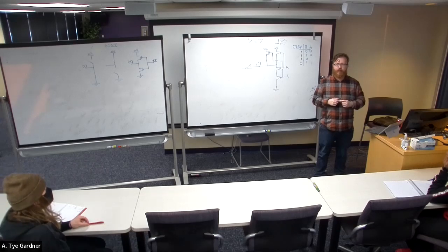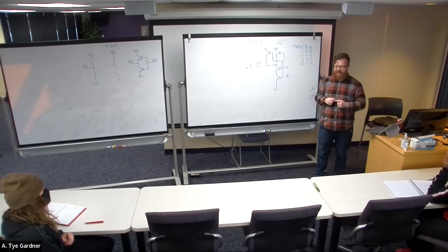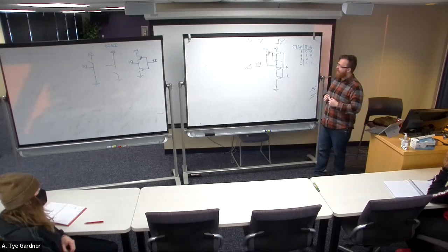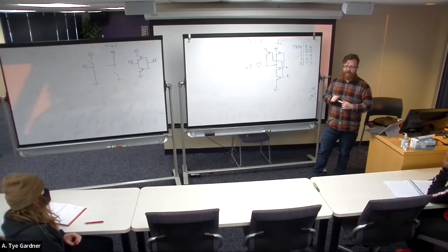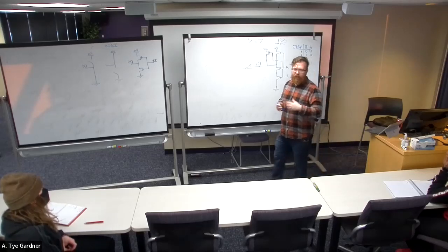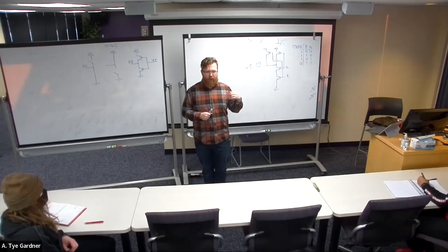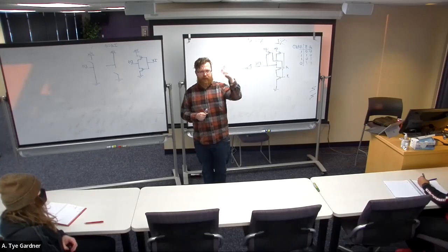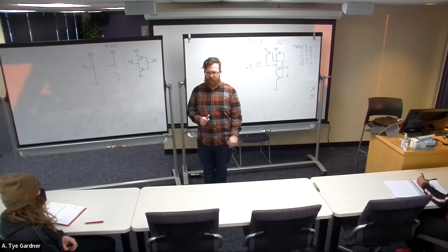Okay, this is why we like universal gates of NAND. This is why we learn to convert circuits into NAND gates: because we want to save ourselves area, thereby saving costs. So if you design a circuit using the sum of products and you get AND gates that feed into an OR output gate, and then you draw the bubbles at the input of the OR gate and draw bubbles at the output of the AND gates, now you have nothing but NAND gates, and you have a size optimal conversion.